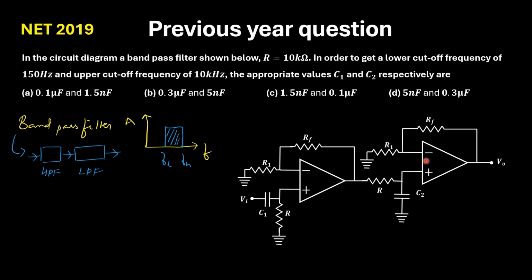And if we go to the second OPAMP, the output from OPAMP 1 is fed as an input, but it is fed through an RC network, and this RC network is a low pass filter. We have already learned from our second video that the frequency will only depend on the R and C of this network.